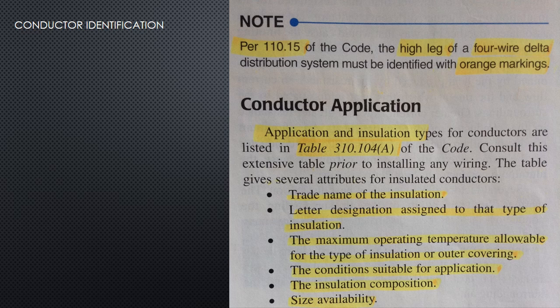Equipment grounding conductors that are insulated must be insulated solid green or green with yellow stripes if 6 AWG or smaller. Larger sizes must be either bare at all boxes and outlets or have the insulation painted green at every box and outlet. See section 250.119 of the code.